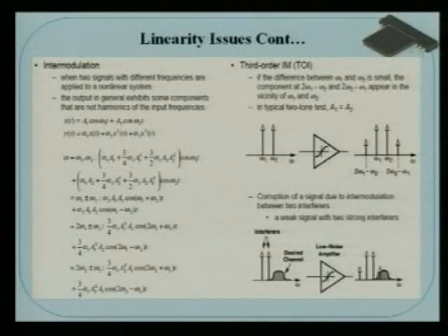So that's why intermodulations are very complex and very important for nonlinear devices, and that needs to be understood. Not only understood, we have to make the necessary circuits to eliminate the intermodulations and increase the linearity of a system. For example, suppose I am designing a cell phone, or a base station. For a cell phone, the linearity requirement is say -10 dBm, but in case of the base station, the signal strength is much higher, because they are actually the center.